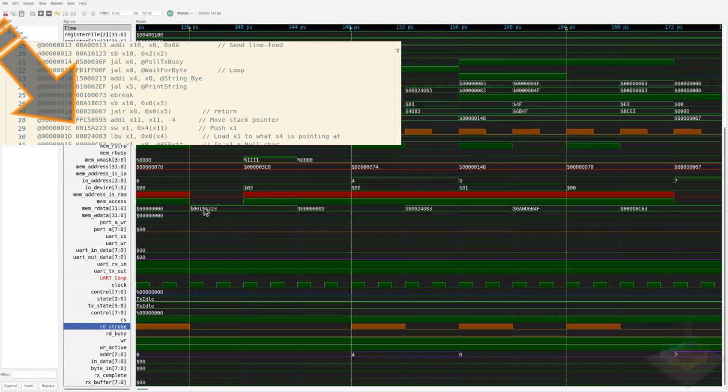So the read strobe is technically what it isn't. We shouldn't expect to see the read strobe itself. Again, the read strobe is indicating the beginning of a read cycle. This allows devices to sense the strobe, then go into their own state machine of some sort and potentially respond either immediately or after a certain period of time as to whether they're busy or not. Normally the read strobe would go high. If the device felt like it was slow, it would raise the busy flag itself and keep it high until it was done fetching the data for whatever reason, and then it would bring it back low.